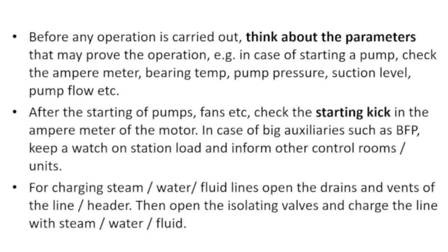Now before any operation is carried out, think about the parameters that may prove the operation. That is, in case of starting a pump, check the ampere meter, bearing temperature, pump pressure, suction level, pump flow, etc. These parameters you may check and think about. After starting the pumps, fans, etc., check the starting kick in the ampere meter of the motor. In case of big auxiliaries such as BFP, keep a watch on station load and inform the other control rooms or the other units also.